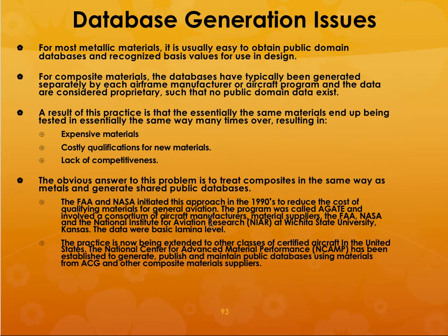Okay. So what are the issues of database generation? For most metallic materials, it is pretty easy to obtain public domain databases. But for composite materials, these typically have been generated separately for each airframe manufacturer or aircraft program, and the data is considered proprietary. So no public domain data will exist.